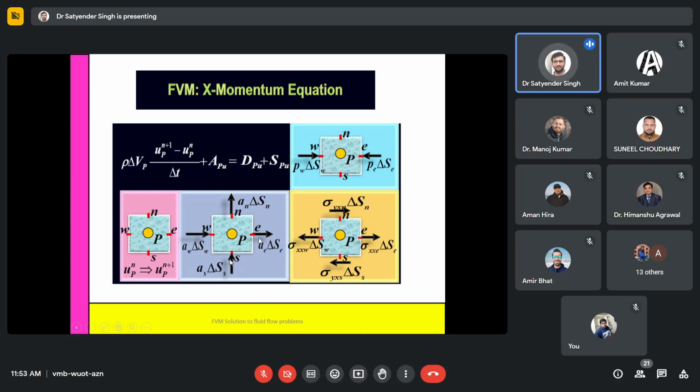They are also available in the solvers, I think, for those who are working with ANSYS Fluent. When you set up your problem, there you will find what treatment has to be given to the momentum and energy equations. Generally we update from first order to second order upwind. So those approaches have to be used here, assigning weightage to particular cell centers by taking the reference of upstream, upstream of upstream, or downstream, and assigning them weightage.